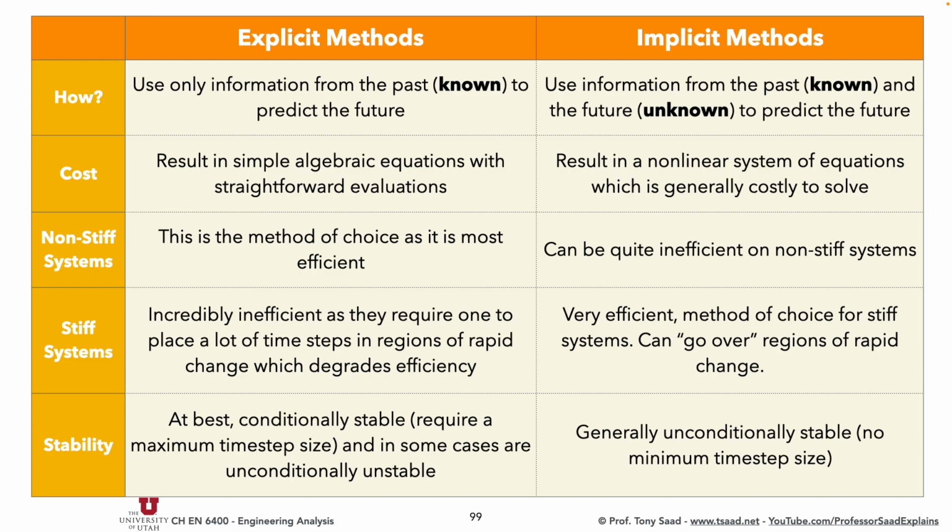Why is turbulence problematic? Why is turbulence so hard to solve? Because we have an infinite range of time scales and length scales. Take the atmosphere for example: the scale of the entire atmospheric boundary layer could be a couple of kilometers high, and the small scale of the little eddy that's spinning next to your hand is a millimeter or sub-millimeter scale.